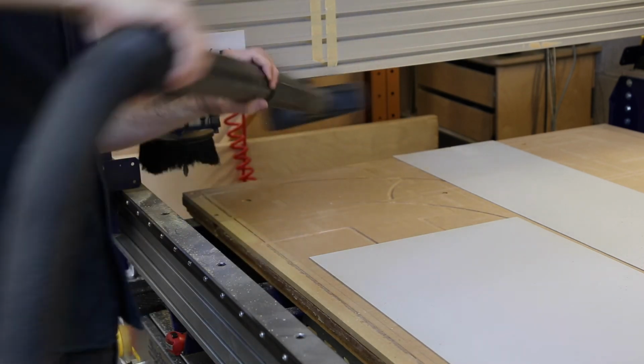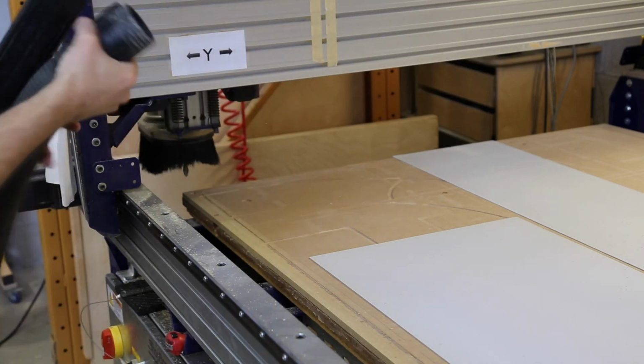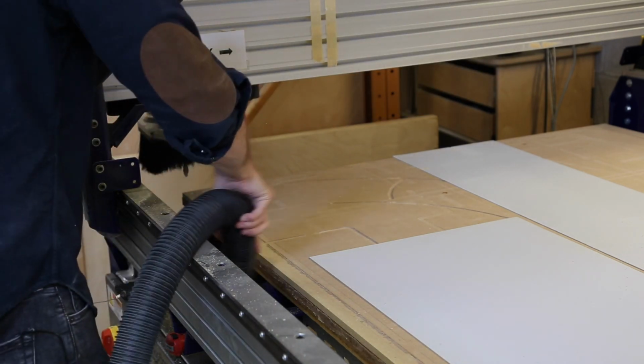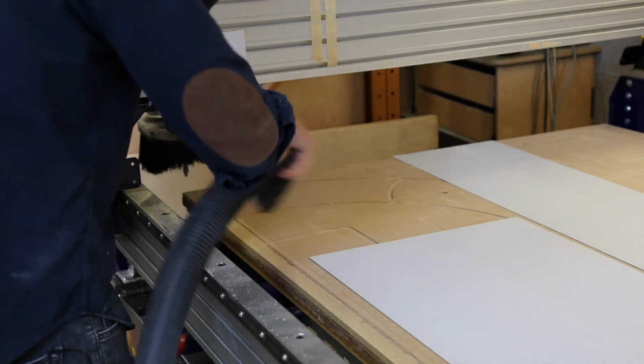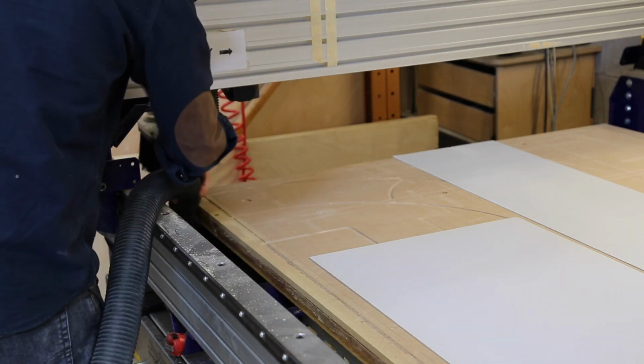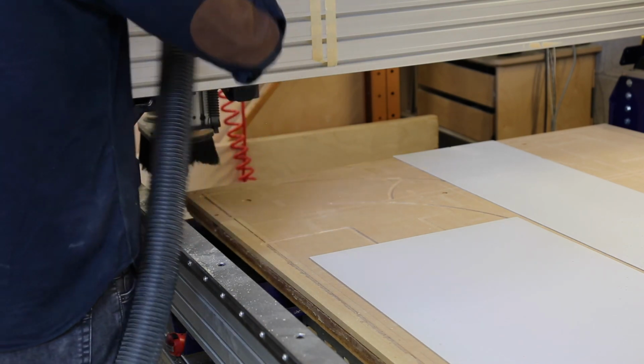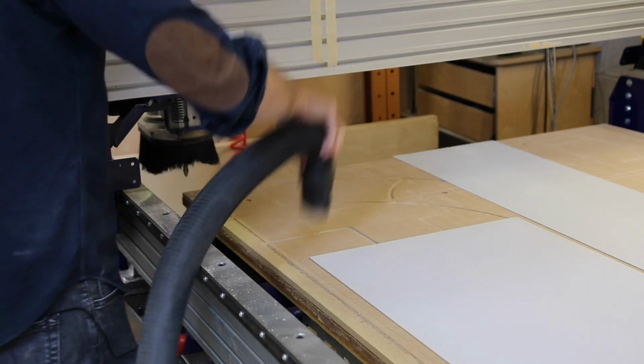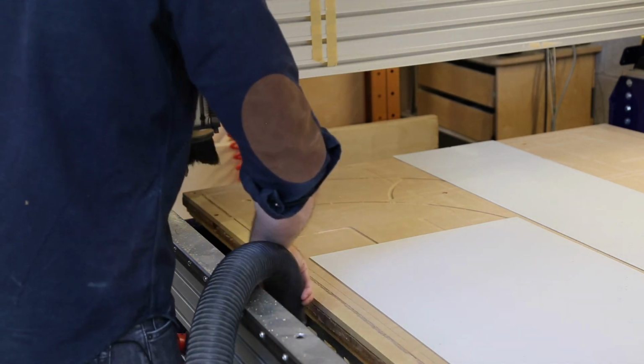To separate your parts from your workpiece, cut through your tabs from the front side of your workpiece with the folding saw that cuts on the pull stroke. This will ensure that you don't splinter out the back of your cut. Use the router table with a flush trim bit to remove the remnants of the tabs from your workpieces.